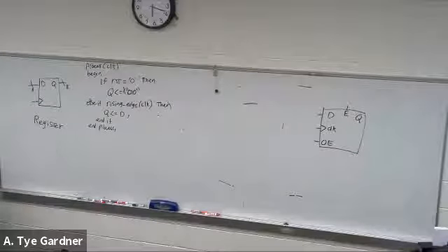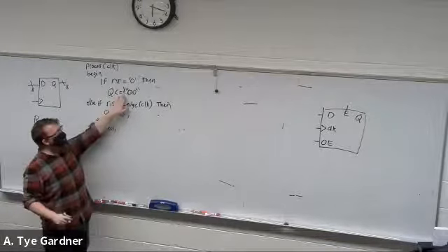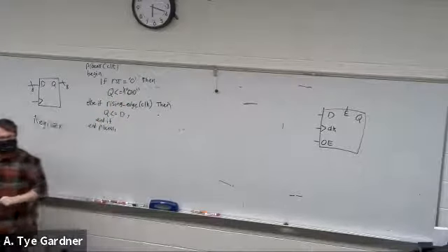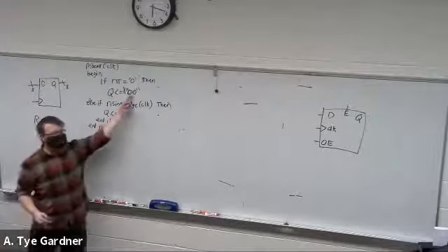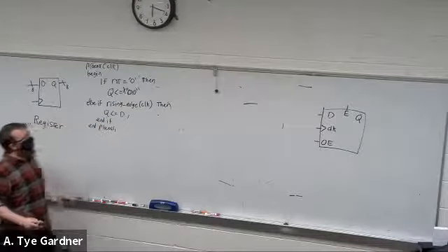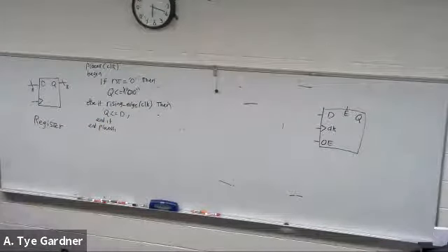Hex. This is saying that what comes after it is hex. That way, this is 8 bits in hex. There we go. This is a nice active low reset D flip-flop. Sorry, D flip-flop based register, right? Because there's 8 bits in Q.